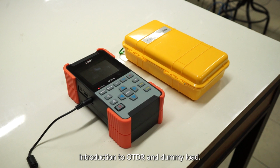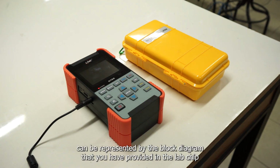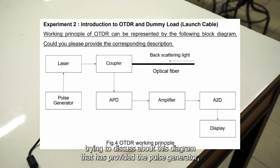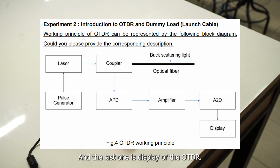Experiment 2. Introduction to OTDR and dummy load. In this experiment, we will cover the working principle of the OTDR, which can be represented by the block diagram provided in the lab sheet. Let's discuss this diagram, which has a pulse generator, laser, and coupler that transfer the optical signal through the fiber optical cable and send it to the APD. It also has an amplifier, an A2D or analog to digital converter, and the last one is the display of the OTDR.